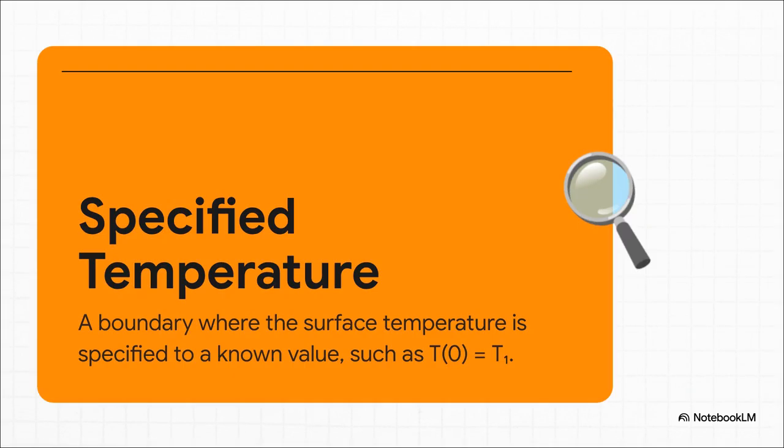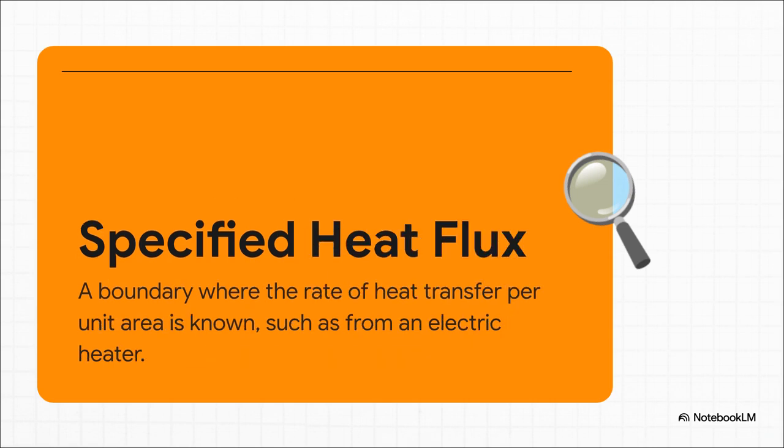The easiest rule you can set is just to specify the temperature directly. For instance, we might know that the inside surface of a wall is being held at exactly 120 degrees Celsius. Bam, that nails down 1 point on our temperature map. It's a fixed anchor.